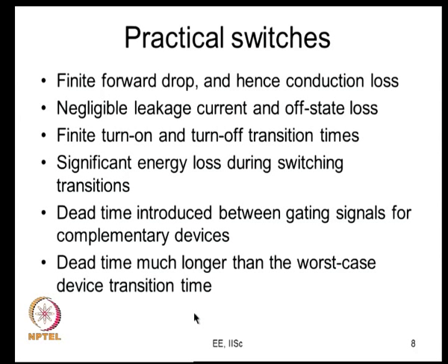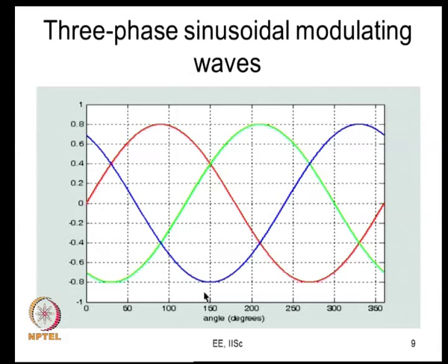I can give you an example. There are IGBTs whose typical device transition times could be of the order of hundreds of nanoseconds, but the dead time would be something like 2 microseconds. That is probably the rise time, etc., and it may still be sub microsecond, but for the entire device transition time you would take something like 2 microseconds. Alright, so let us go further and see more clearly what dead time is.